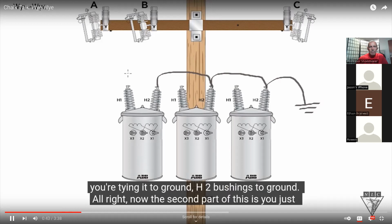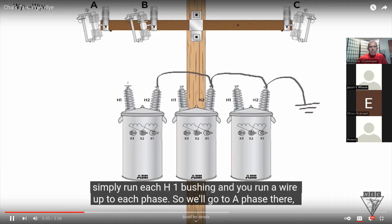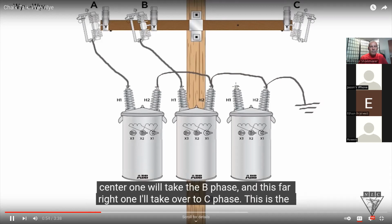Now the second part of this is you just simply run each H1 bushing and run a wire up to each phase. So we'll go to A phase there, the center one will take the B phase, and this far right one. Just a reminder, H1 to a phase, H1 to a phase, H1 to a phase, all H2s.